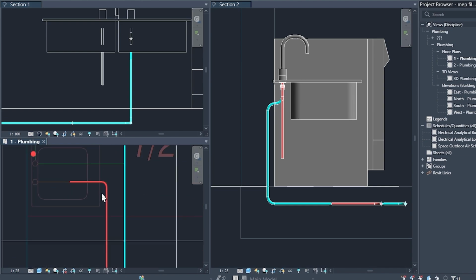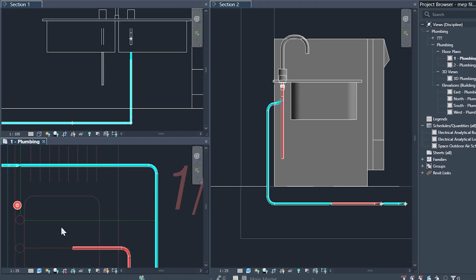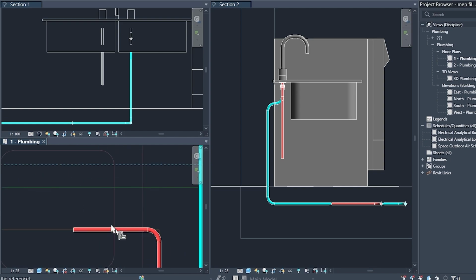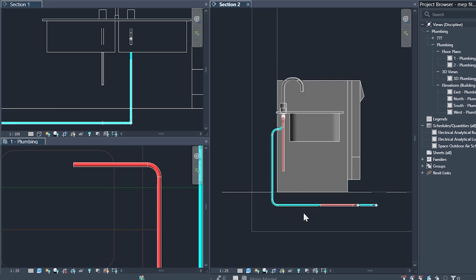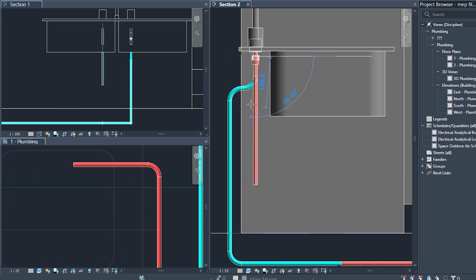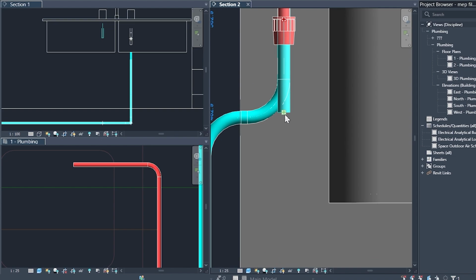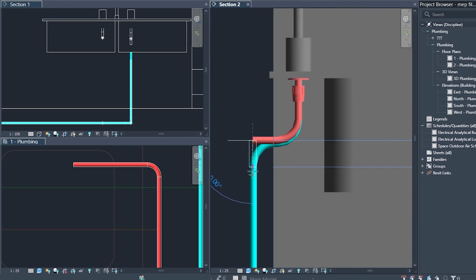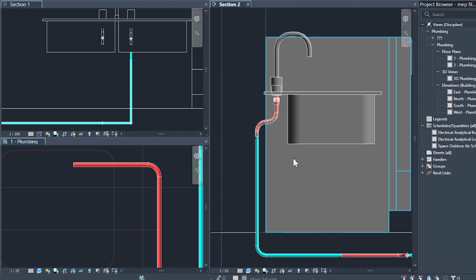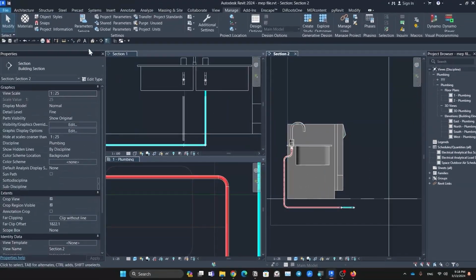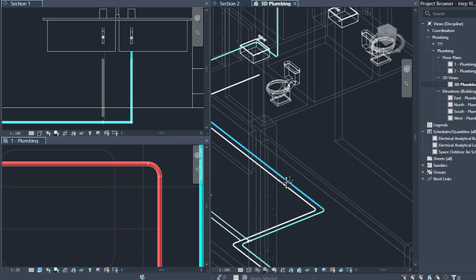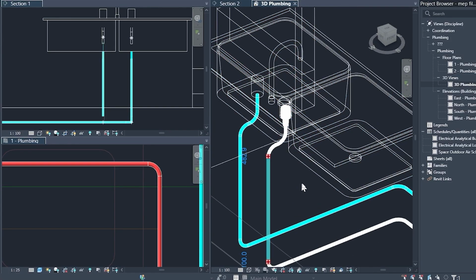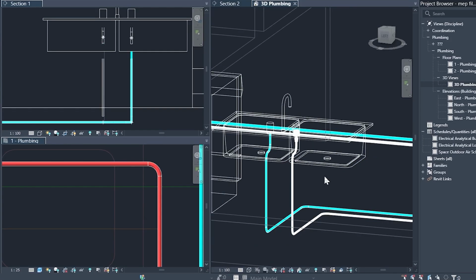junction in here. And because I have it already, I just align this part with this part, and now I have the pipes. I have to bring it up and draw a pipe and do this, and then trim these parts with this part. And then if we go to 3D, not this 3D, maybe 3D plumbing, you can see we have the connections in here without any problem.